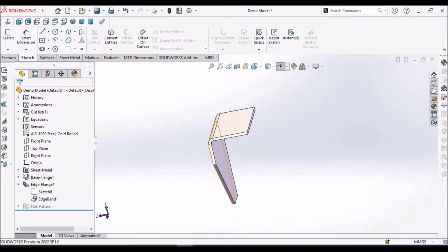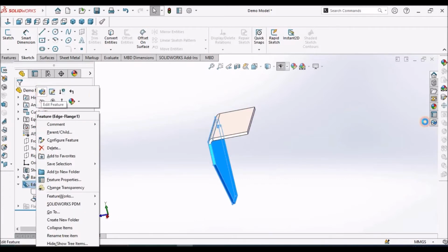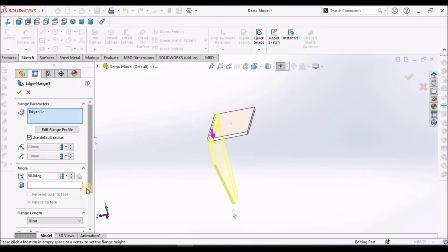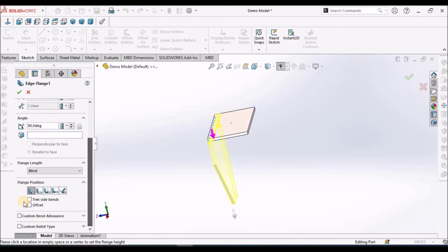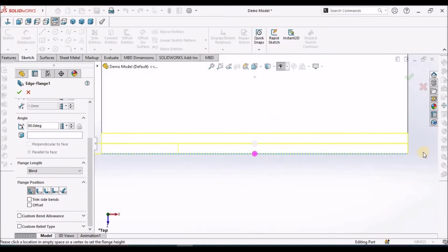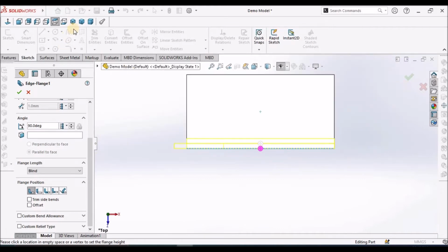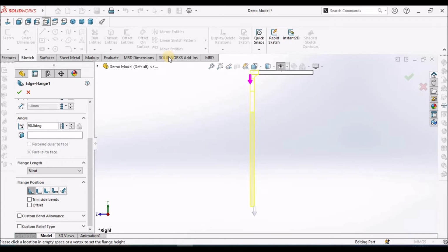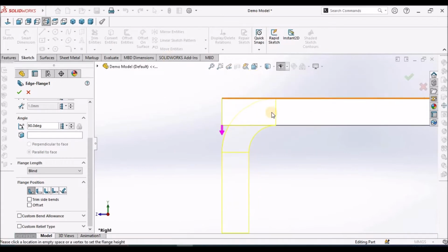See here. One thing we need to verify is that this one should be material inside. When I check from the top view, it should be exactly inside. In the right side view, if you can see, the bend is formed inside this edge. That is important.